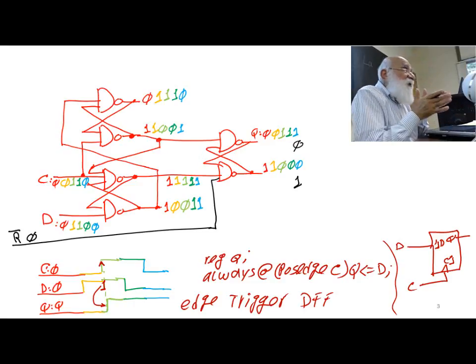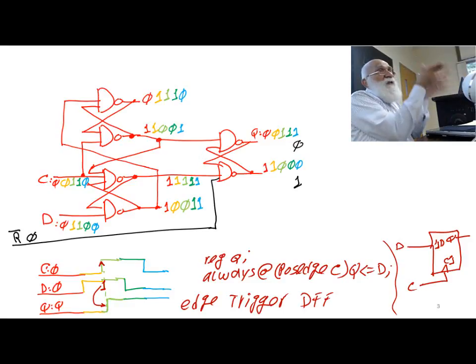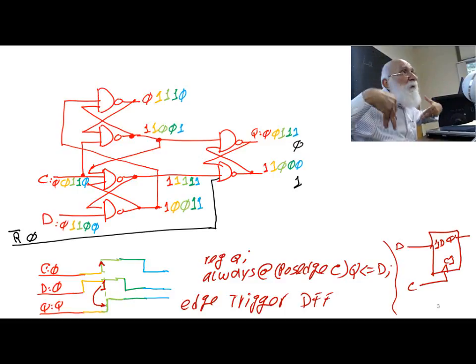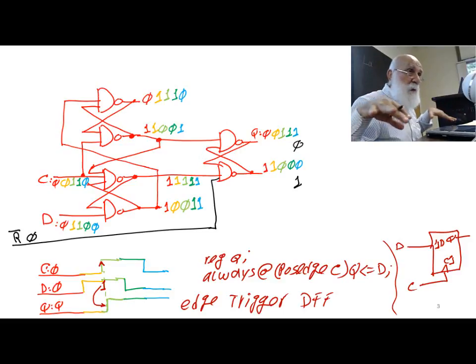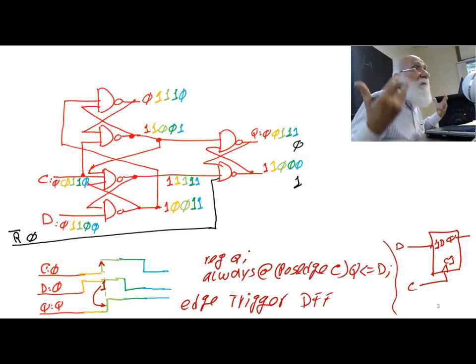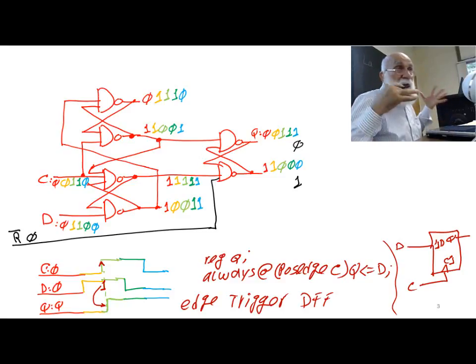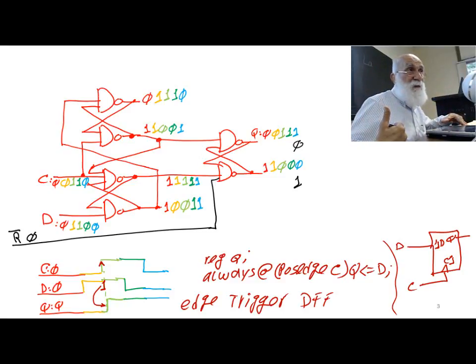The reason it is not permanent is because it's not changing the stages before that. It's just going right to the output and changing the output of the gates. It's not changing the memory. It's not changing the state of the circuit. It's just changing the output. That's why it's not permanent. If I want to make it permanent, so that when it becomes active the output resets, and when it goes back to 1, which is normal mode, the output remains at that reset value, this is what I interpret as reset.